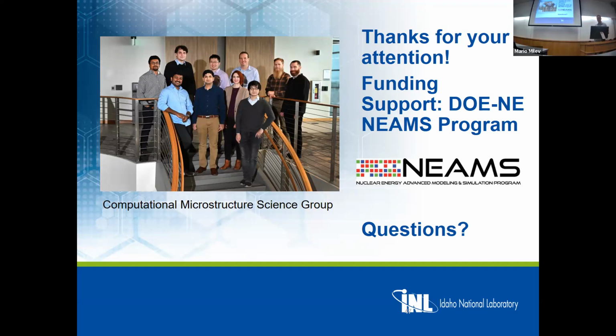So the second question: if we compare the new scale models in the phase field open source code and Marmot, how do they compare, apart from Marmot being specific to nuclear materials, like for grain growth? The model in phase field and Marmot, which one? The model would be the same. The difference would be that Marmot would have specific values for the grain boundary energy and grain boundary mobility in UO2, whereas the base grain growth model in MOOSE phase field is for copper.